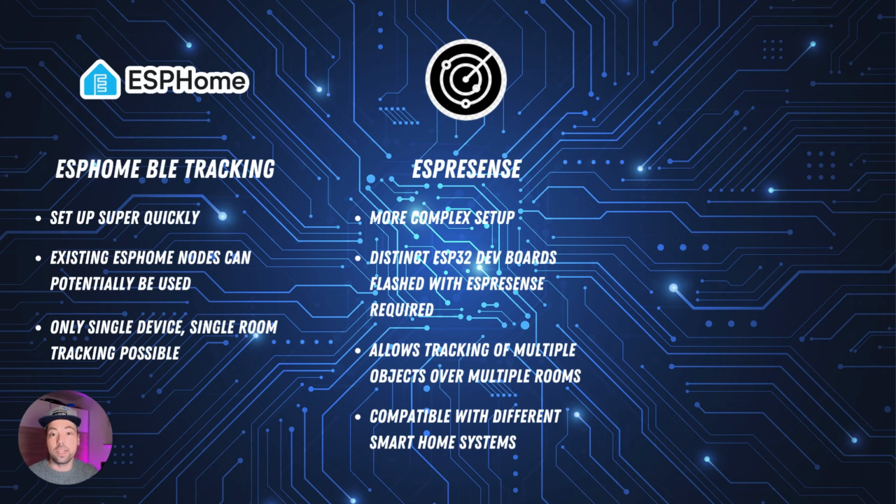There are multiple of such solutions out there, but I'm just going to stick with ESPresense because that's the solution I use. ESPresense allows you to track multiple objects over multiple rooms. And this is done by placing distinct ESP32 nodes, which are flashed with ESPresense, in multiple rooms of your house. For example, you can place 1 or 2 nodes per room in your whole house, and with this you can track the objects within your whole house.